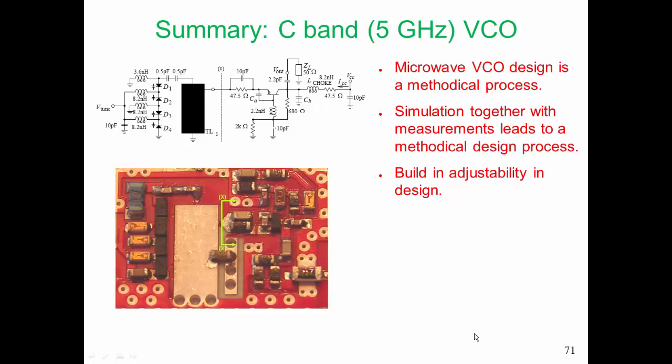If we're on chip, we're going to use biases to adjust things such as capacitance values, but we must build in adjustability. In fact, one of our challenges is how to do this adjustability automatically without a human being in the loop. And if we can do it automatically, we will be able to adjust for operation at different temperatures and as our circuit ages.